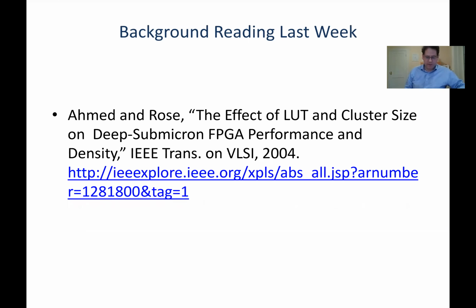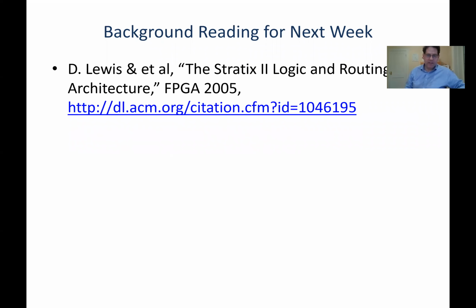Background reading last week was on logic block design. We're not going to get all the way to that one this week, but we will next lecture. The assigned reading for this week is also on logic architecture. Basically, the Stratix 2 architecture from Altera, because this brought in a major change in how logic architecture was done that most subsequent FPGAs have adopted, something called the fracturable lookup table. So a bit more complicated than the lookup tables we'll look at today.